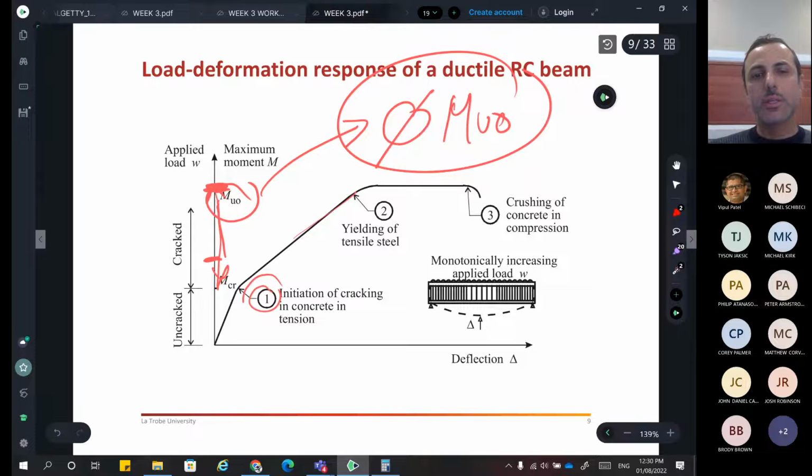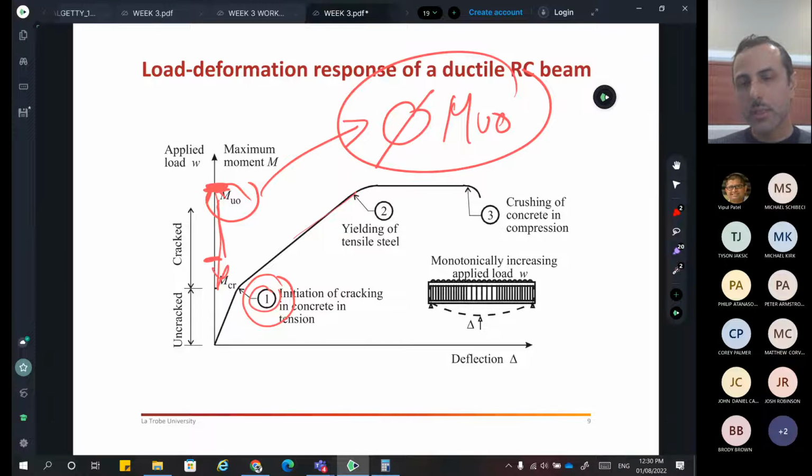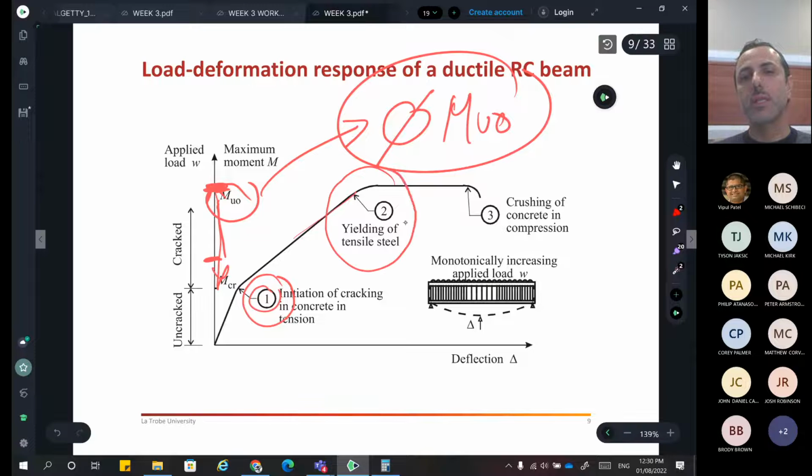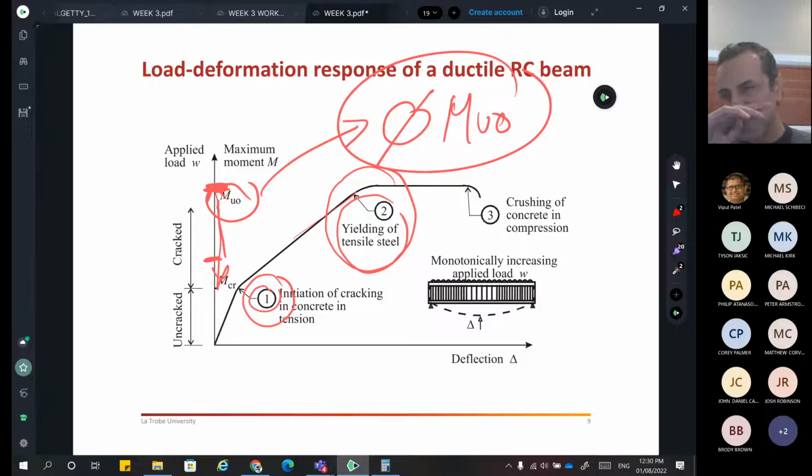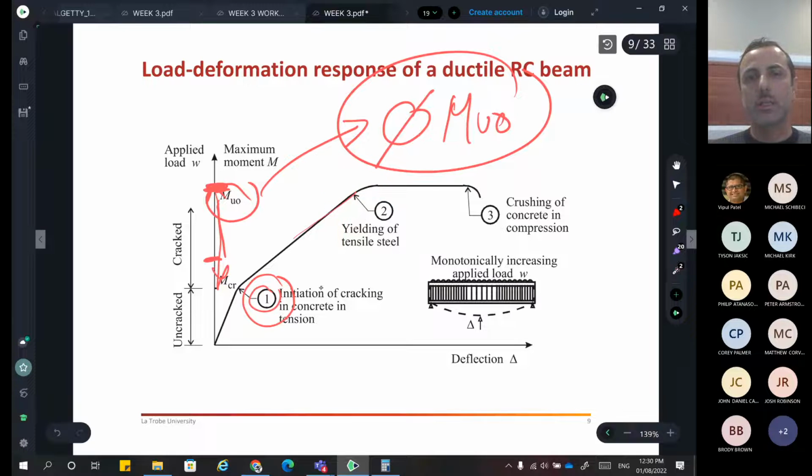Now, the first thing you need to understand is the beam is going to suffer from cracking, which is okay. It's only going to crack on the tension side, and that's why we want it to happen, so the steel gets into business. Then the other failure it's going to face is the yielding failure. The steel is going to reach its maximum capacity. And yes, we design for this as well.